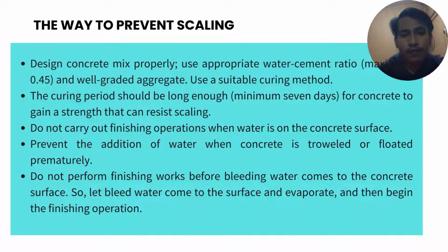The ways to prevent scaling. First, design the concrete mix properly. Use an appropriate water-cement ratio, maximum 0.45, and well-graded aggregate. Use a suitable curing method. The curing period should be long enough, minimum 7 days, for concrete to gain a strength that can resist scaling.